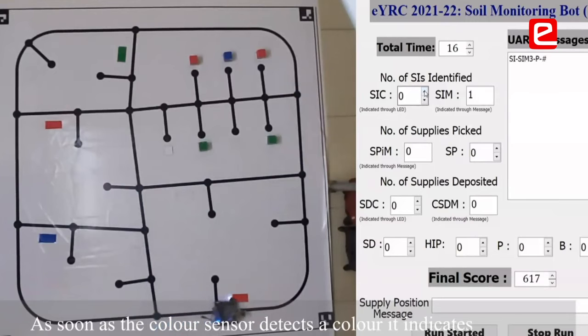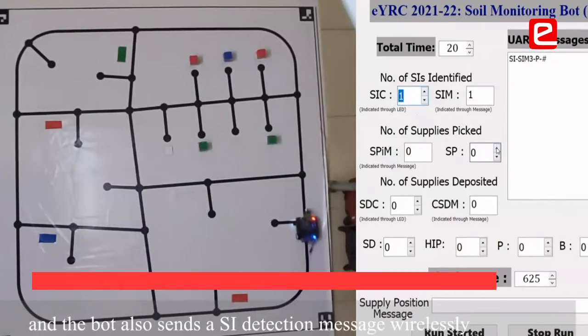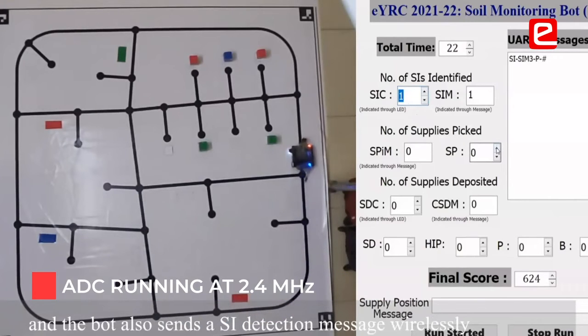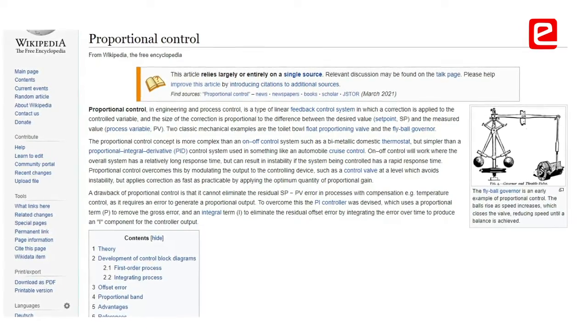What was your update rate for the bot's orientation? As soon as the ADC finished sampling, it would send it to the line following module directly. I think the ADC was running at 2.4 megahertz. If you have such high sampling rates, maybe then you don't need PID, and a P controller will do. Yeah, I mean, it's that delta coding versus sigma delta coding debate. So simpler hardware, but more power.